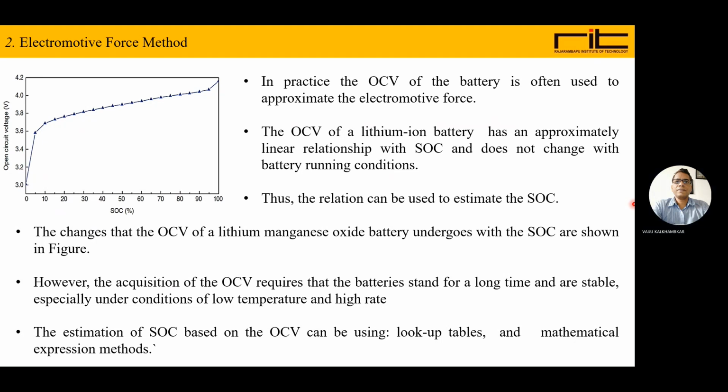So, for the electromotive force method or the open circuit voltage method, values can be noted and a table can be formed, and for a particular voltage level we can note the state of charge and that can be used, or we can use mathematical expressions.